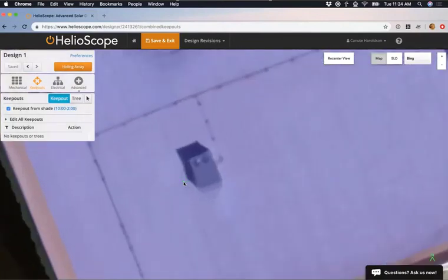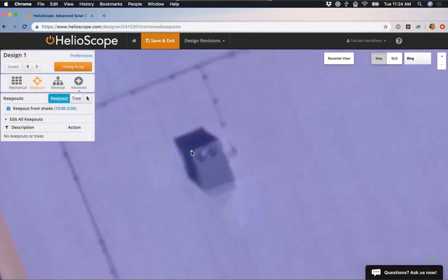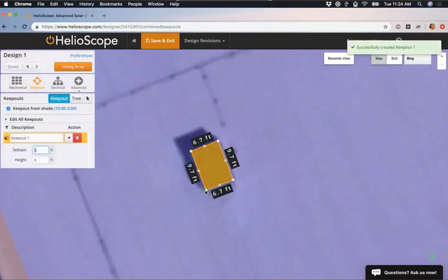I'm going to zoom in on this HVAC unit here, and just like drawing a field segment, I'm just left-clicking that first point, second point, and this is a rectangular obstruction here. So I'm just going to hold Shift and then double-click to finish that shape. Now we can call this an HVAC unit if we want to. We can give it a setback. We can even give it a setback of 1 foot, not 10, and a height of 5 feet.